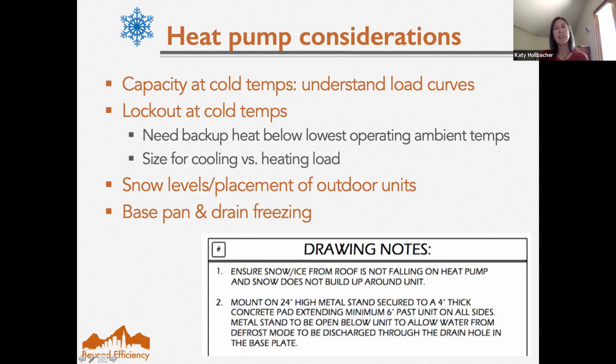Just to highlight one thing here, understand the load curves. I was involved in a project once, not local, a Northern Idaho project, where the mechanical design build contractor had a heat pump specified and thought that it was going to meet the loads of the building. Then I realized in looking at their specs that they had just taken the rated output, which I think was listed for 32 degrees, and yet the design temperature in this region was 5 degrees.